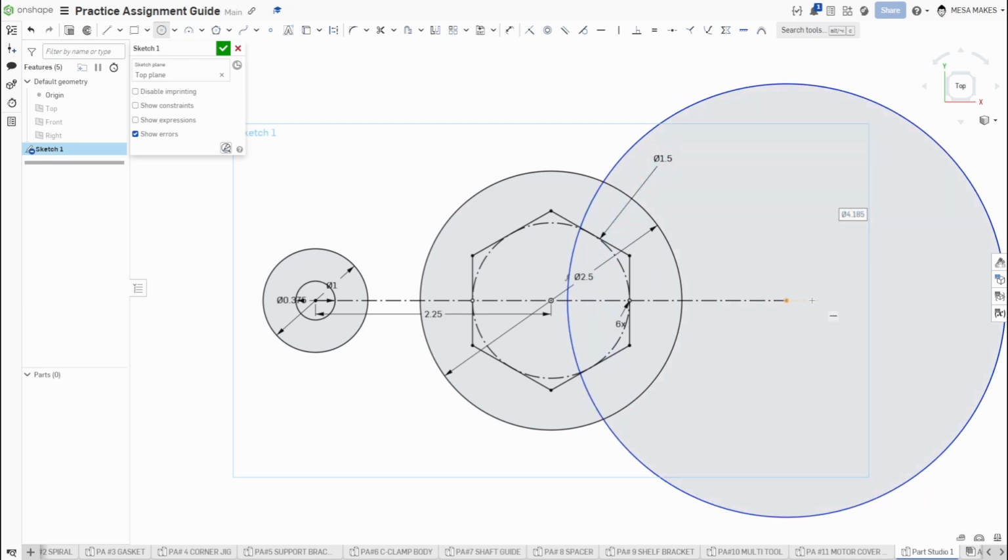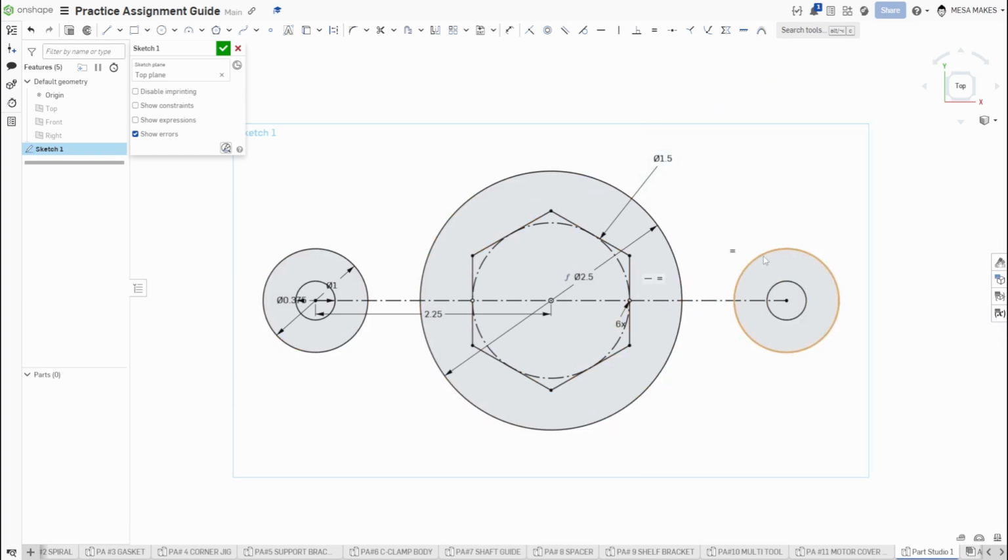The other thing I can do is when I do circles. Obviously that's not the right size circle, and that's not the right size circle either. So I can say, hey, this inside circle and this circle need to equal each other, and this outside one and this outside one need to equal each other. And now we're set up pretty even. The way I like to do it though is just by using the mirror command. The problem with doing that is order of operation. So I'm going to show you these lines first, and then I'm going to show you why we would mirror.